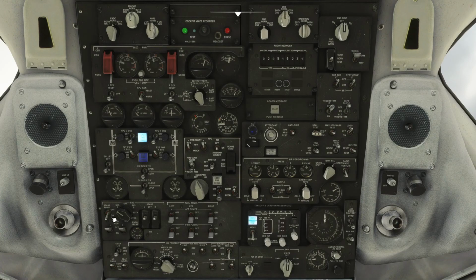So we close that, start pump off, ignition selector off. We can take the APU generators off the bus. We can turn off the APU bleed and the APU, as well as the air conditioning slide switches can come on again. Boston Center, JetBlue 1755, just checking we're clear to cross 4 left.